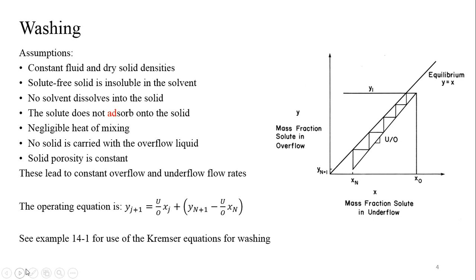So washing. We're going to make some assumptions here. The assumptions that we're going to consider here, that we have essentially constant fluid and dry solid densities. The solute-free solid is insoluble in the solvent, so we're not getting rid of any of that. No solvent dissolves into the solid.